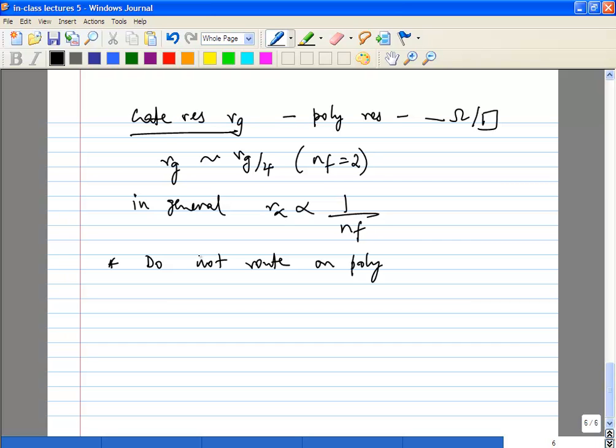Okay, there are certain cases where people do poly connections, and those are done for standard cell gates. You will see standard cell gates where, for example, if somebody is building an ASIC and they want to do an auto place and route involving millions of gates, which means each gate should be laid out as efficiently as possible. And once you have thousands of gates, timing and other things become limited by the number of gates rather than by the delay of each gate.